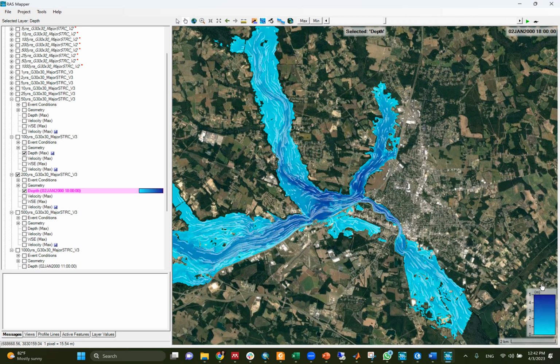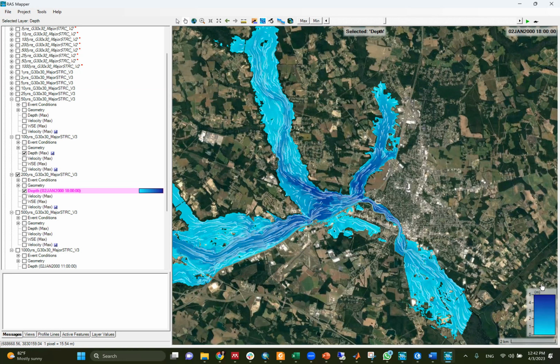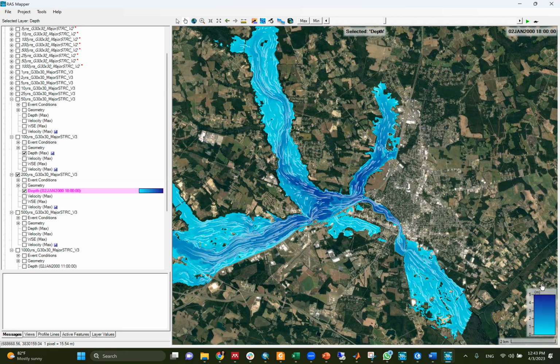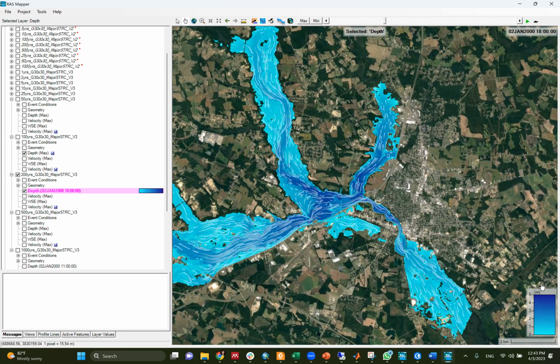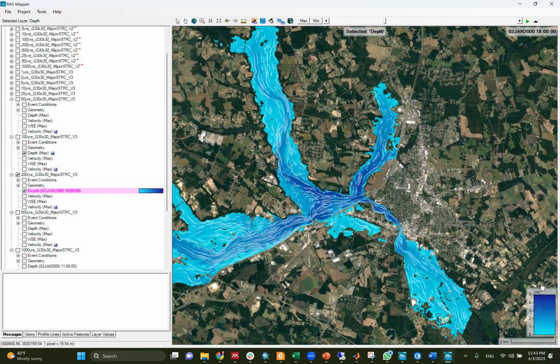So what we will do step by step, and I believe that you guys did it in your homework, is that I'm gonna send you the hazard maps and send you the building points. You will do the extraction of the flood depths at each building point. So you will know the building archetype. Is it residential, commercial, or what building archetype 1, 2, 3, 4, 5? And you will know the flood depths at this building. Okay, so you will know two things. You will use these two to run a MATLAB code to identify a damage.